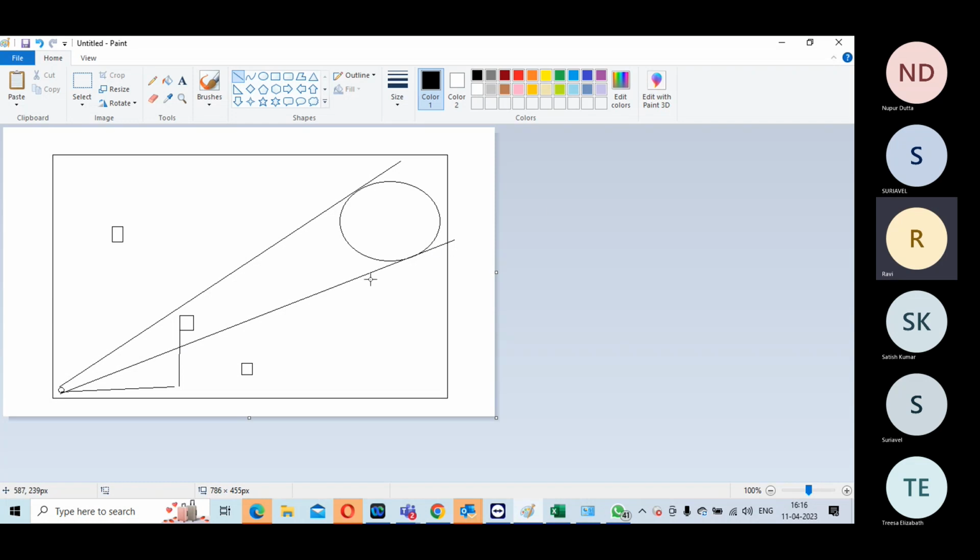But have this because I want some things to stick in your mind. Okay. And the next part is, you know, this particular path is called the stem of the tree. And here, maybe you don't want any crosstalk. If you want, just for that particular net, you can add it as a shielded net. But the clock getting to your flop connection, that's called the leaf net. Root net, leaf net, middle net, stem, all these are there.